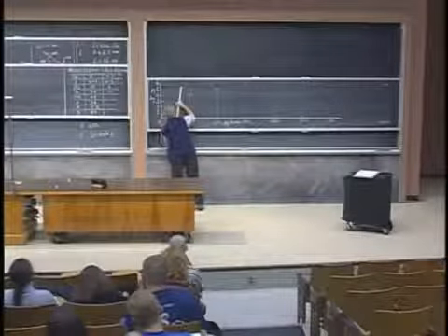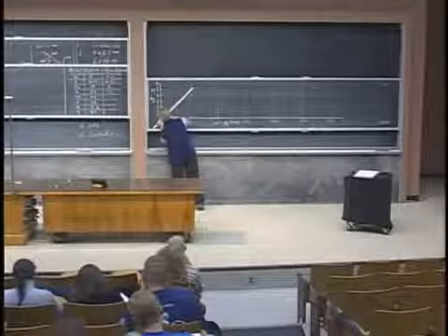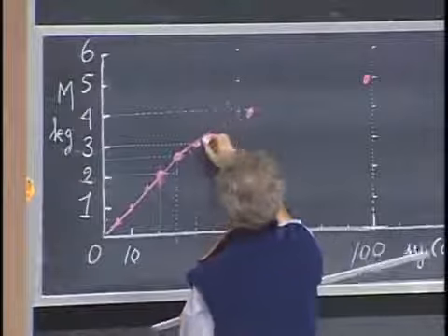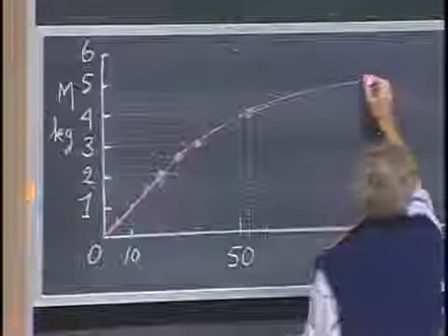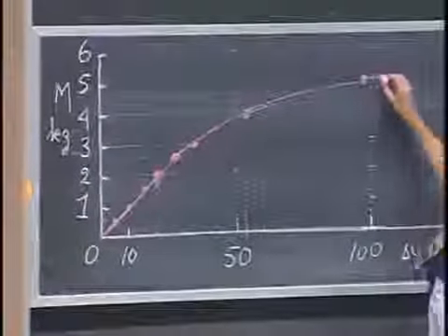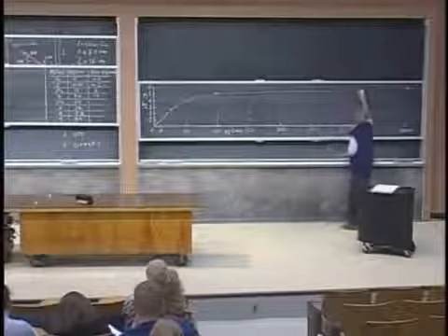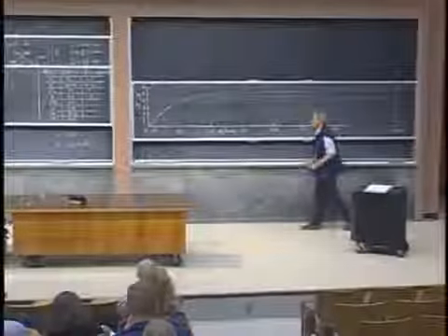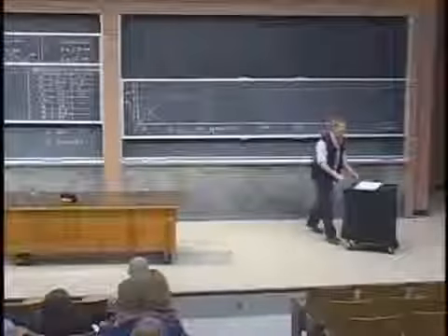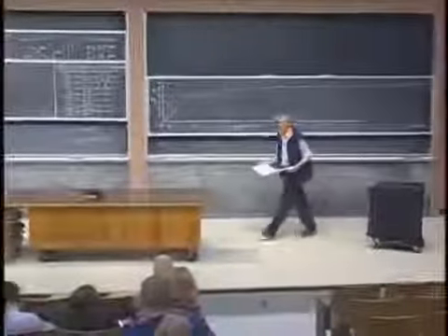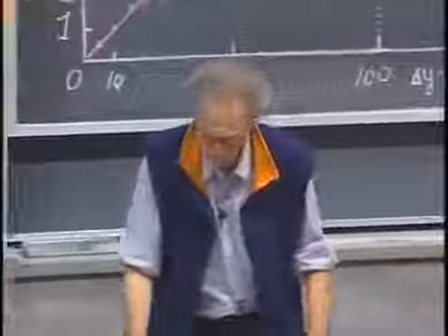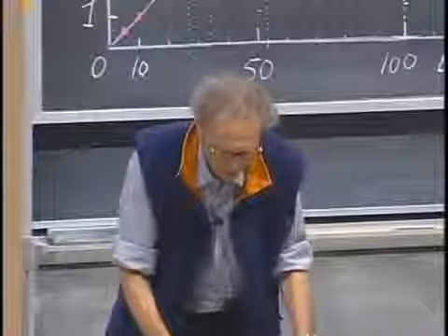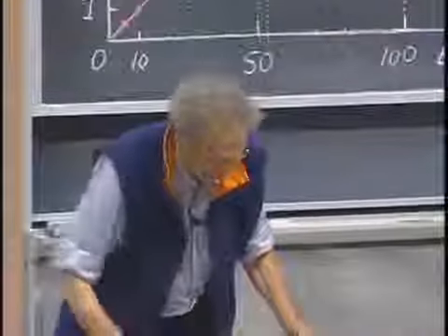Very linear in the beginning, and it starts to bend over, and you draw that line any way you want to. And then it breaks. And so we can now actually make an attempt to calculate Young's modulus from the data. Of course, you'll have to select a portion where you think that the data are reasonably linear.